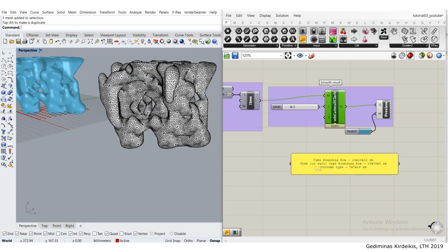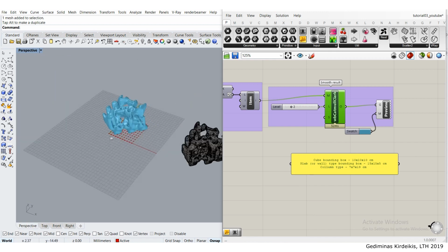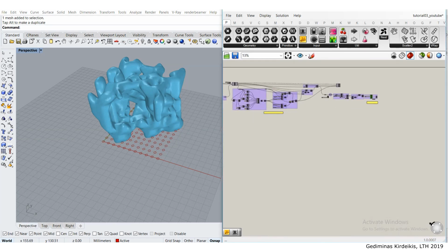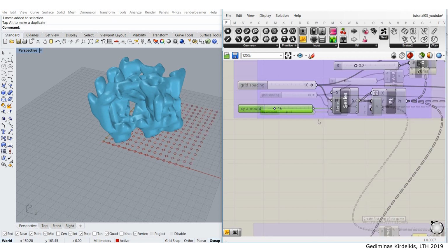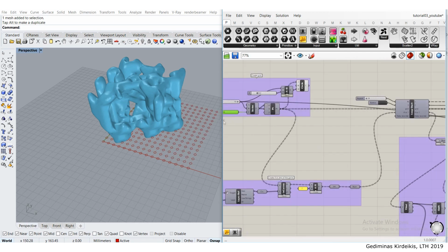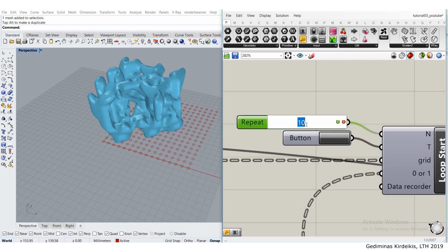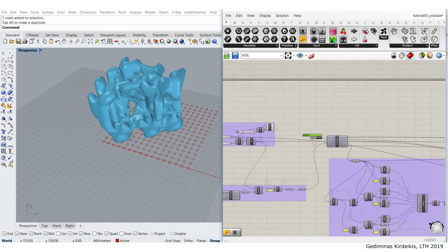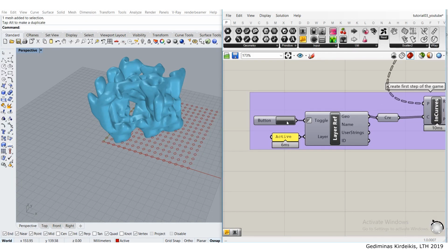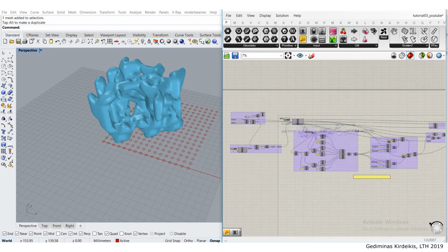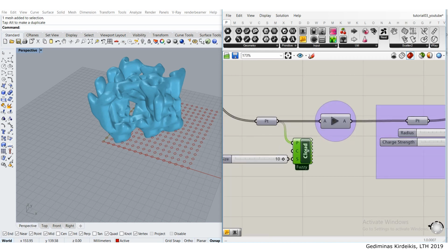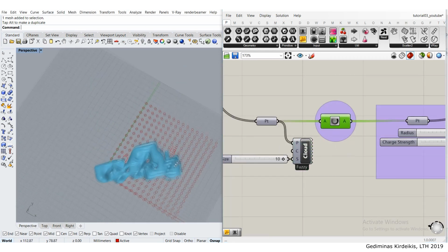For a slab or wall type bounding box, we have 15 by 15 by 5, right? So let's see it. If it's 15, here we need to use 16 for X and Y, and 5 here. Let me run the simulation again. Reset, reset, and let's just check it out as a mesh, right?